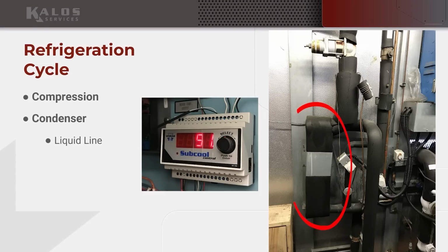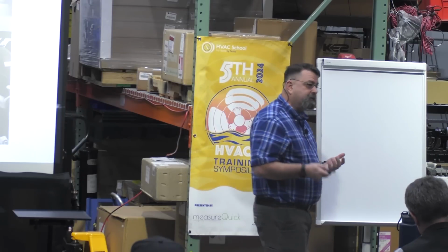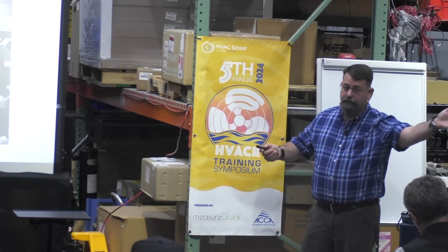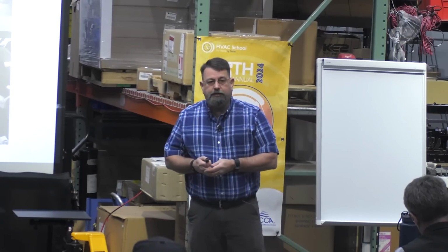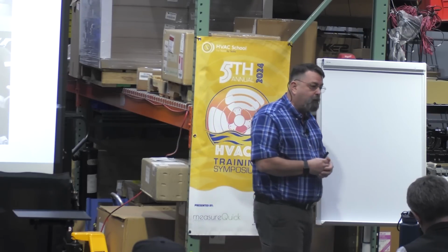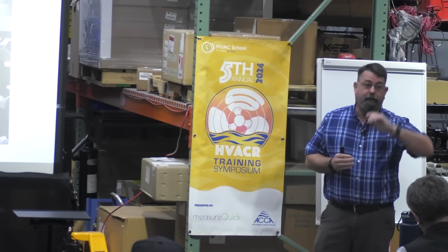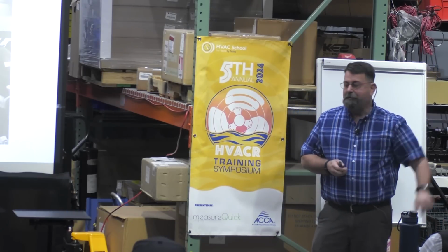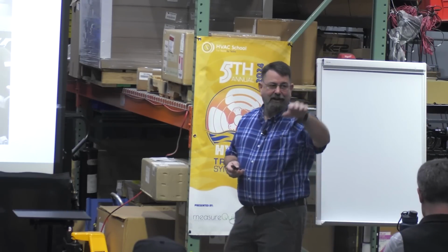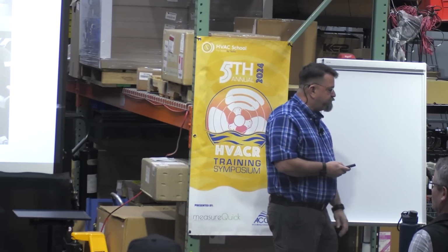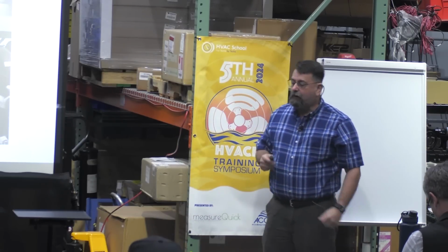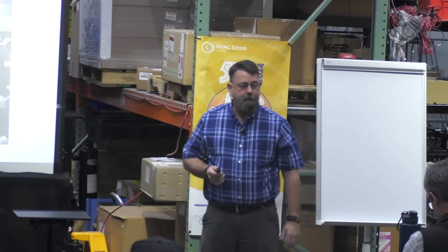We want to guarantee that we get that full solid column of liquid to my expansion device, right? And in this pipe, going from here all the way to that farthest case, maybe a couple hundred feet. Nice, that's not uncommon. So I've got to cool it down a little bit more, right? Or I'm going to flash, especially when that liquid line goes up into the ceiling across that hot store, you know, the heat rising in that store. Probably going to cause a liquid flash. So I want to subcool it for that reason, right?